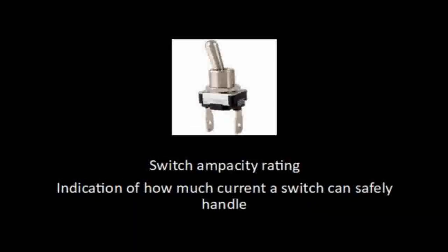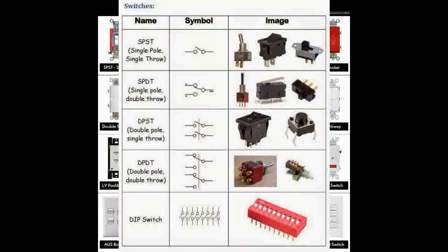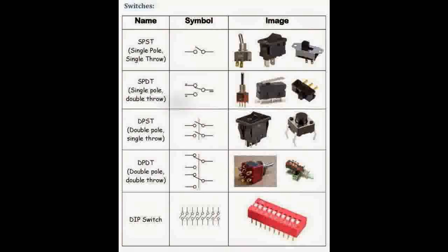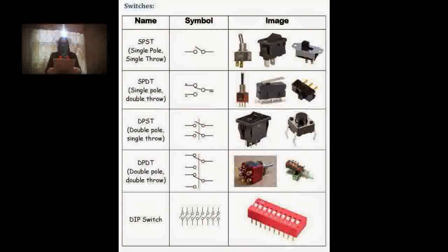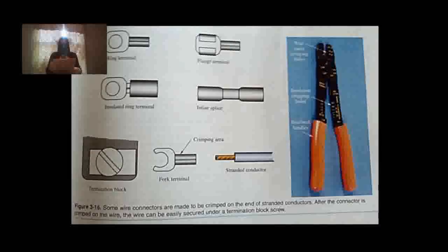For example, a toggle switch is rated at 1 amp and 24 volts. A current in excess of 1 amp will burn out the switching circuitry inside of the switch. If the 24-volt switch is connected to a 240-volt circuit, it may fail to open the circuit sufficiently to stop the flow of electrons. This action will result in a dangerous situation that can melt the switch's insulation and short-circuit the switch.